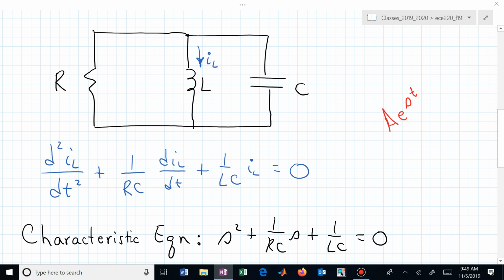So now to make the damping less in this circuit, you actually increase the resistance. That's a little counterintuitive. You think, oh, increase the resistance, you're going to increase the damping. But in this parallel RLC circuit, it's just the opposite. You increase R, and the damping now diminishes.